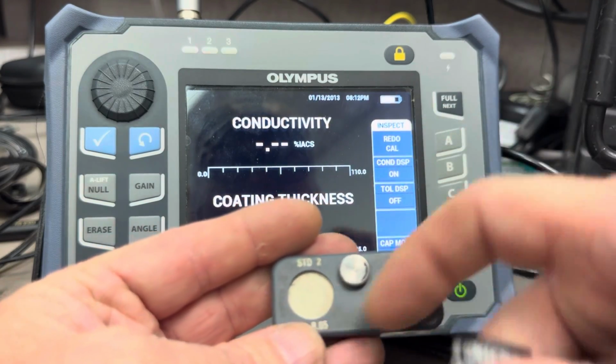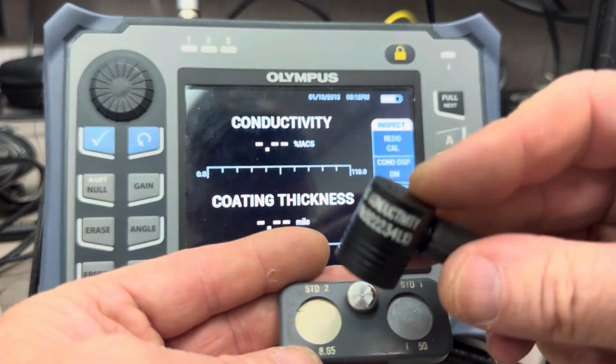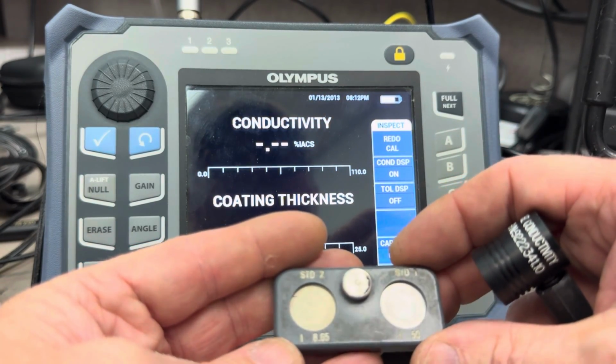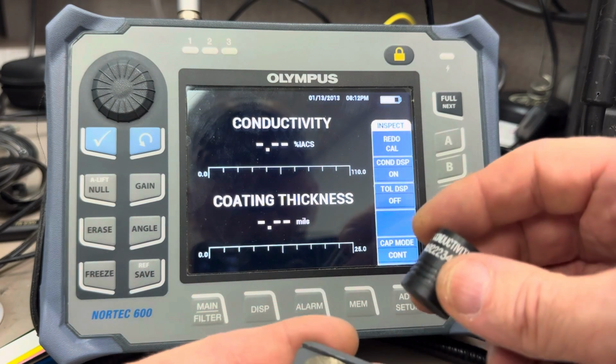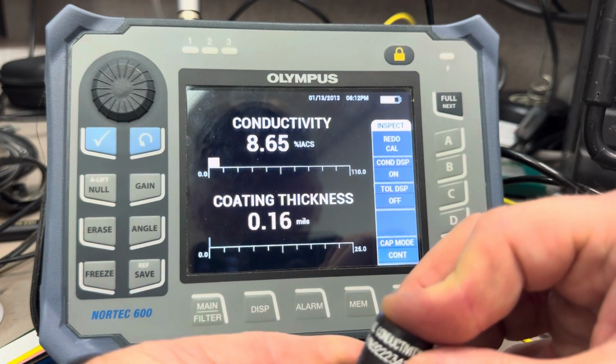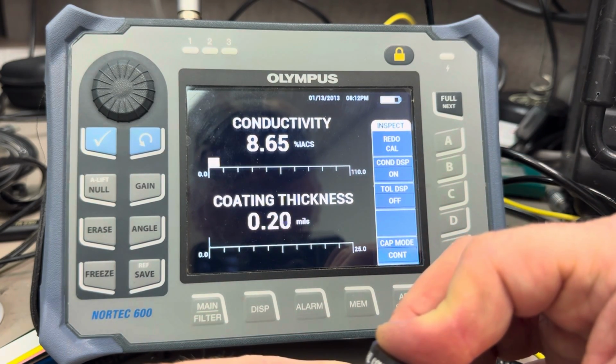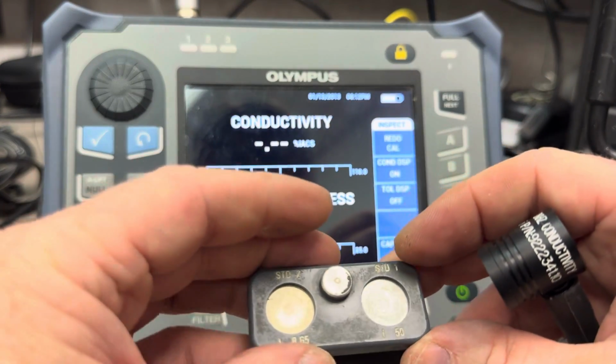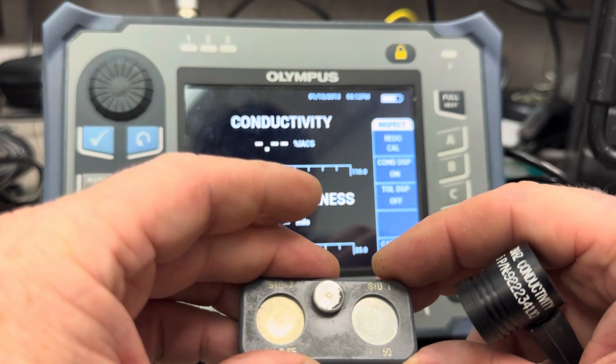And obviously there's a hole here, my coil diameter is too large, so if you just set that on there, you're not going to get a good reading because you'll have liftoff. So flip it over on the large surface, and I'll hold my probe down, 865. That's dead on balls accurate, like they say in My Cousin Vinny. And then the next one is 50.